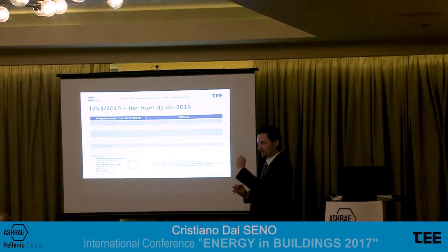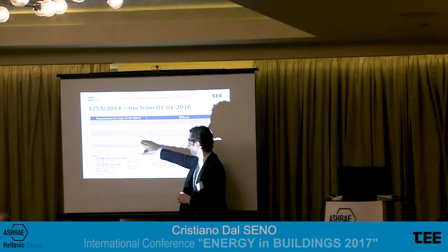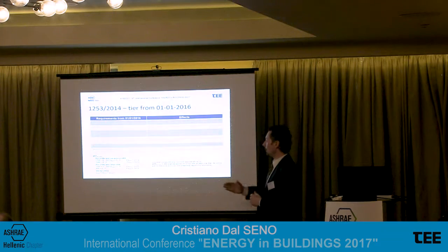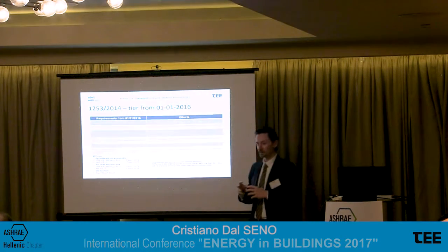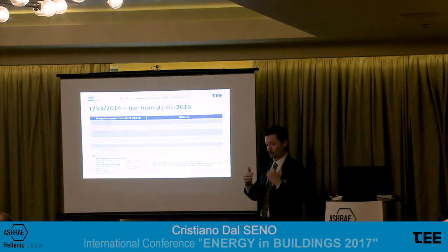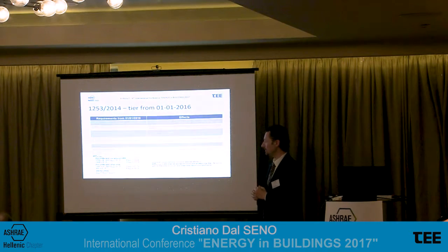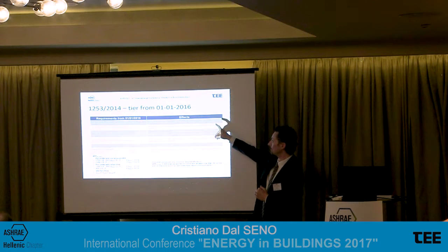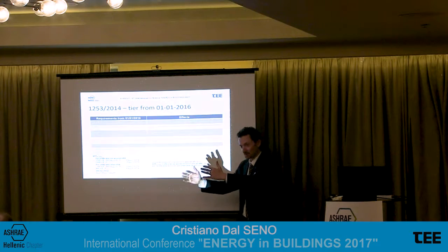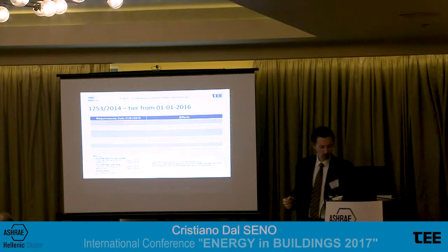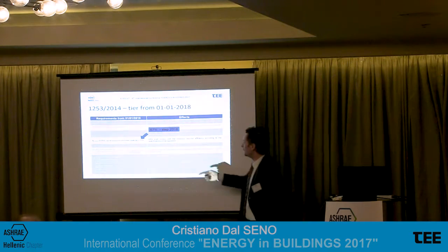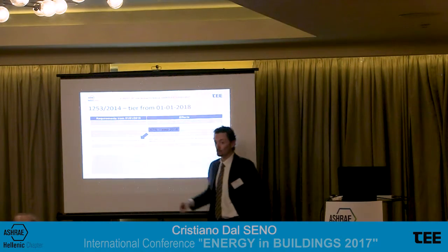Given this idea, we have to comply with the 67% in terms of efficiency for the recuperators. We have formulas to calculate limit values, and then our units should stay within these limit values. We must say that these formulas were valid for units produced after 2016 until the end of this year, more or less. What's happening for next year? They increased the efficiency to 73.